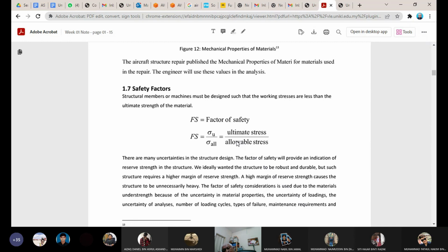The 50% margin is where you account for error, for the environment that can make the structure fail prematurely, and also for the case where the assumptions in the design were wrong. So that 50% is available to avoid any failure if the structure goes beyond what it was designed for, the structure design capability.